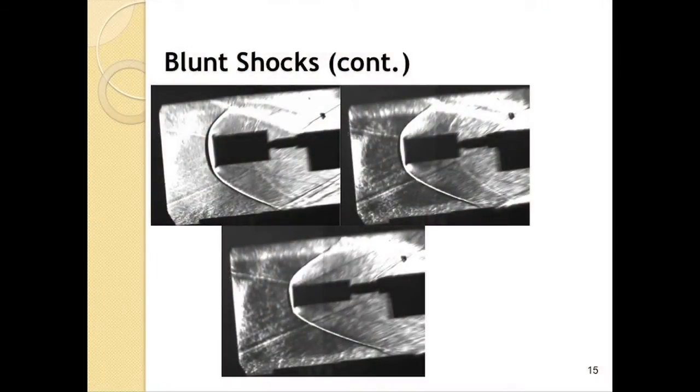And in terms of the detached shock, Chris was telling us earlier about this subsonic pocket that forms. And in the front of the model, you see a small white section before the black line of the shock wave, and that's basically it. And here, obviously, our model isn't a perfect sphere. There's many angles tapering off. So we did have quite a bit of percent error, but it was only 10%, which is considered a pretty good estimate.